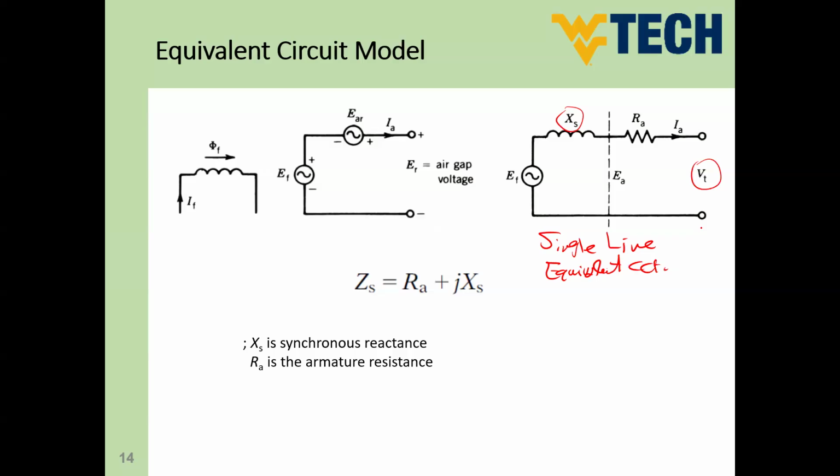Synchronous motors, we still have some in our industry, but it's very little compared to the other type of motors like the induction motor. I mean the field-based machine. However, we have the permanent magnet synchronous motor. It's used a lot in industry, and it's even preferred over the induction motor due to the higher efficiency. Okay, and later on we will discuss why the efficiency of the synchronous machine is higher than the efficiency of the induction machine.